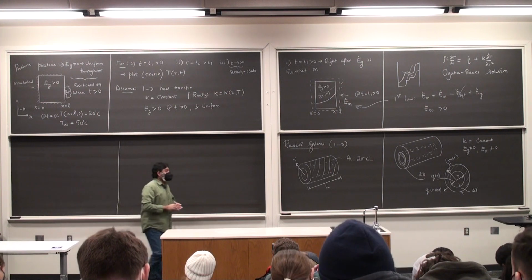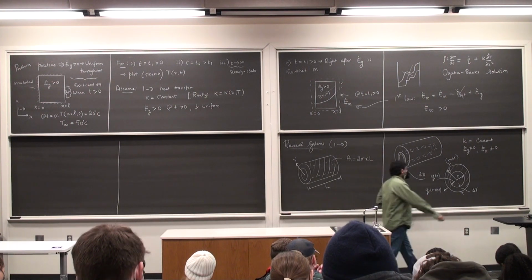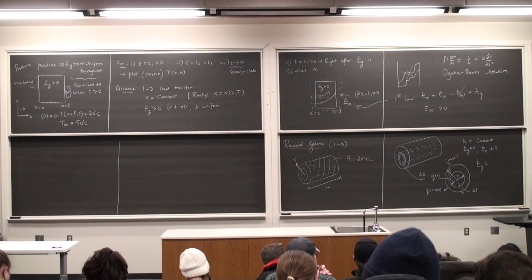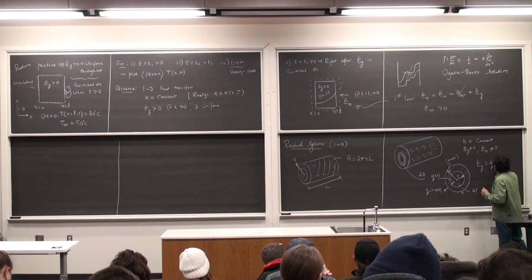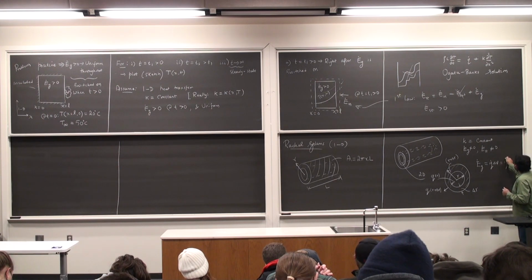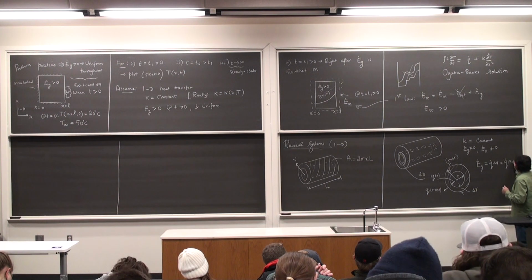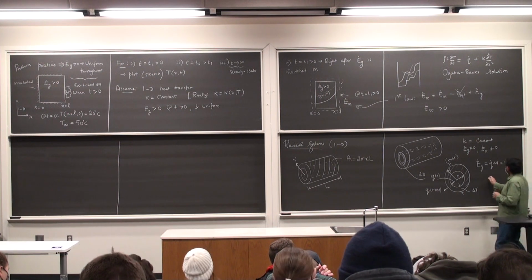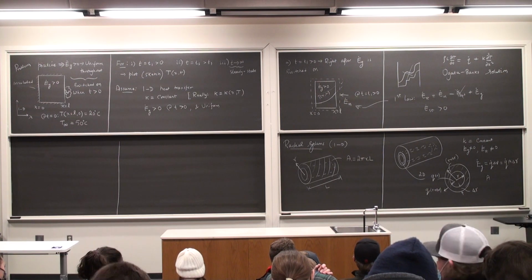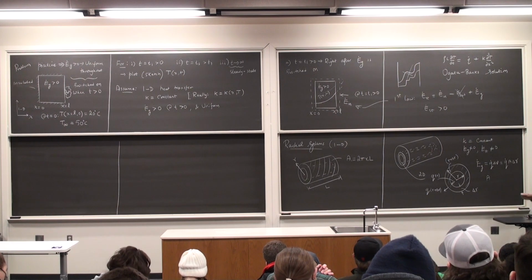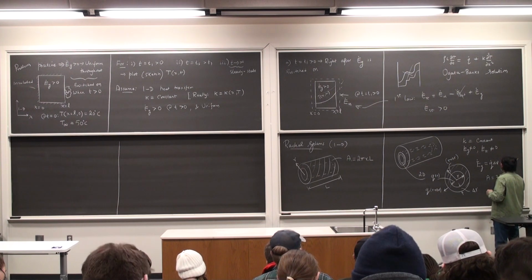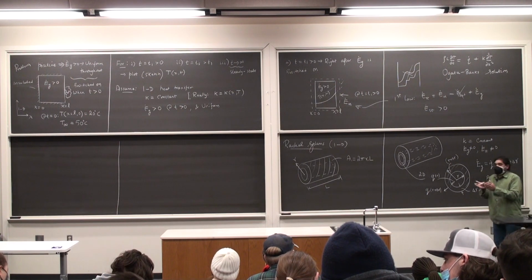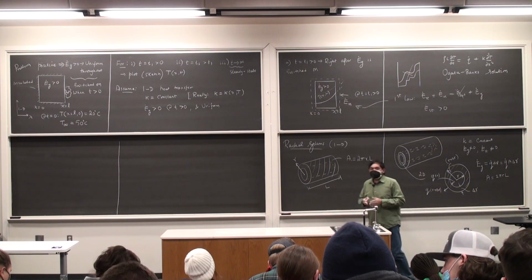And we also discussed the following last time. If I look at the volumetric energy generation term, E dot G, we wrote this as Q dot times delta V, which is Q dot times area times delta R, where the area A could be written as 2 pi RL using the inner ring radius, or you could use the outer ring radius, but in the limit of delta R tending to 0, those small terms or higher order terms will essentially drop off.